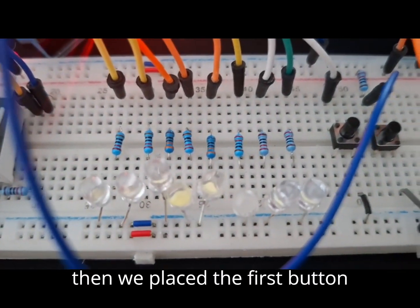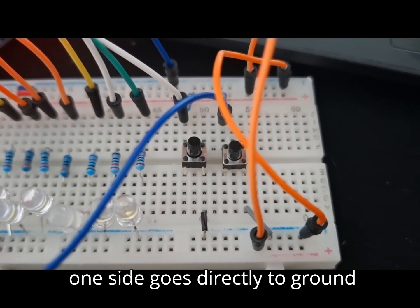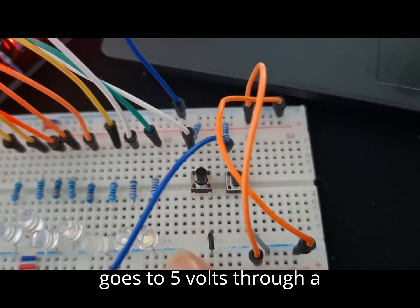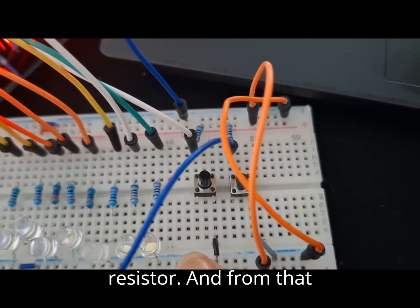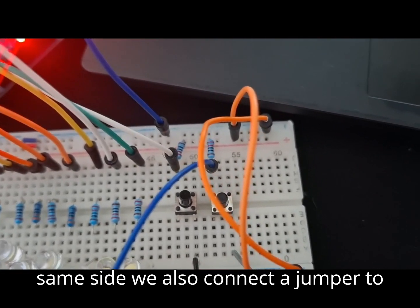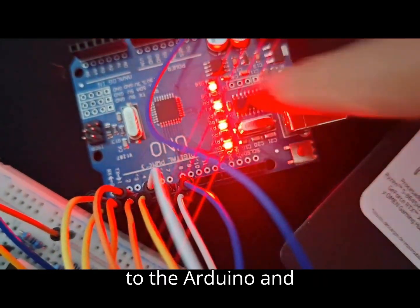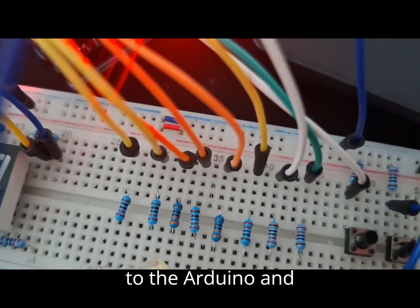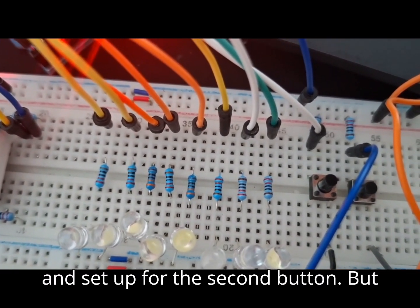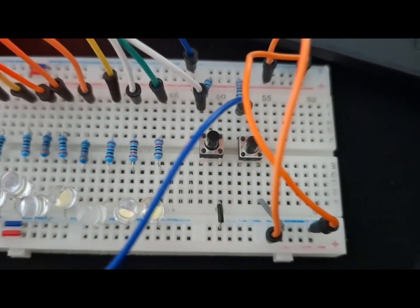Then we place the first button. One side goes directly to ground here, and the other side goes to 5 volts through a resistor. From that same side, we also connect a jumper to pin 8 here on the Arduino, and we repeat the exact same setup for the second button, but this time the jumper goes to pin 9.